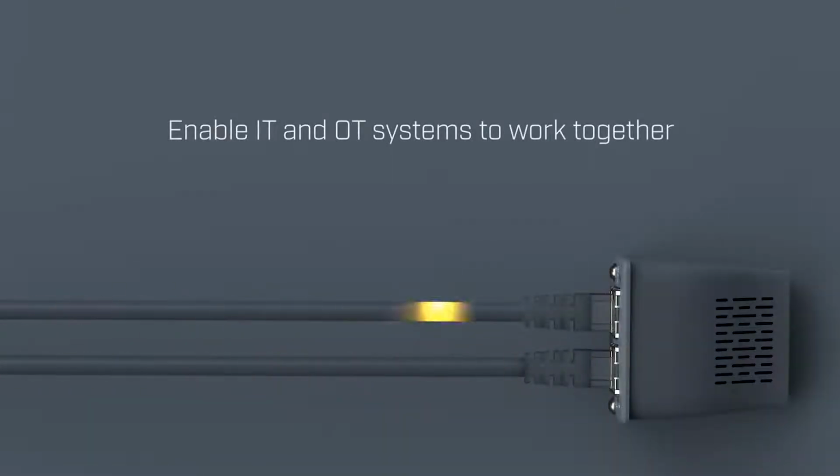But basically, simply put, you have the control traffic provided by Profinet or Ethernet IP, for example, on the same wire where you grab diagnostic data using some information protocol similar to OPC UA or something like that. You could also have an ongoing video stream from one part of a factory floor where they take motion pictures of a core process that's being brought up over the same network to a high performance computing platform in the IT system, where we do some AI analysis of what's going on on the factory floor. And everything shares the same network.